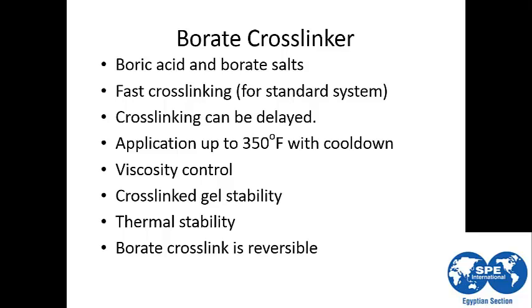We can control the viscosity. The crosslinked gel is stable against shear and has thermal stability. The Borate Crosslinker is reversible, so it means that we can break the Borate Crosslinking system.